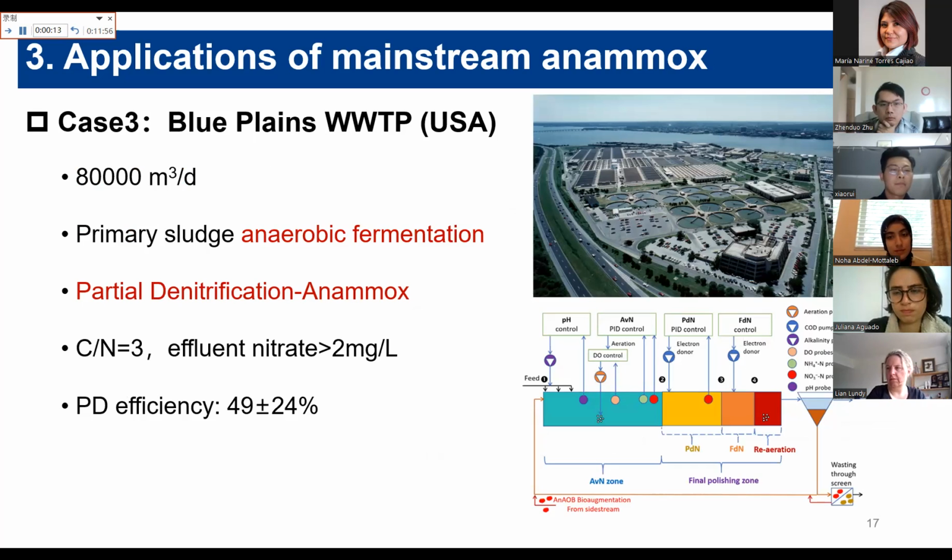And the third case is the USA Blue Plains wastewater treatment plant. Different from partial nitritation and Anammox, it adopts partial denitrification combined with Anammox because PNA technology is not stable, but PDA technology is more stable and can achieve less N2O emission. So it's more feasible for carbon neutrality in the future.